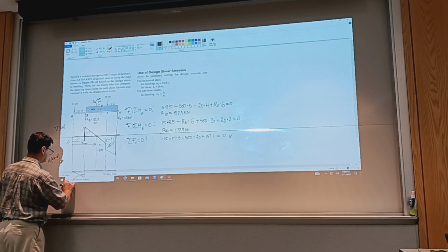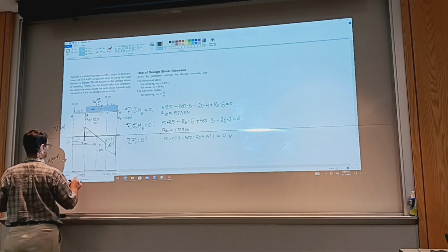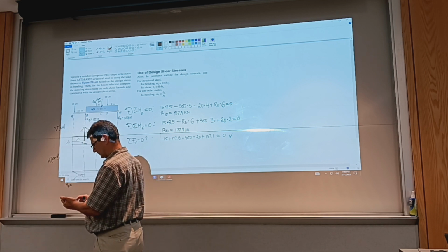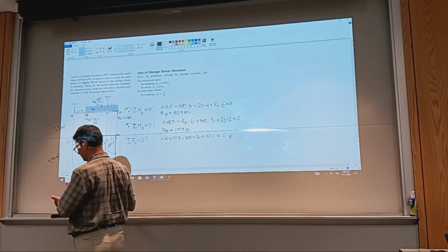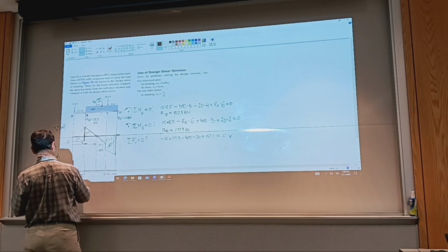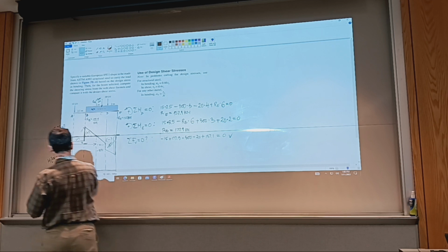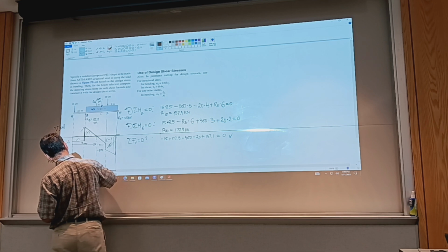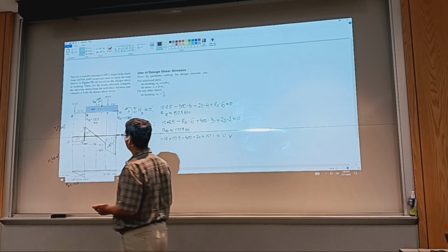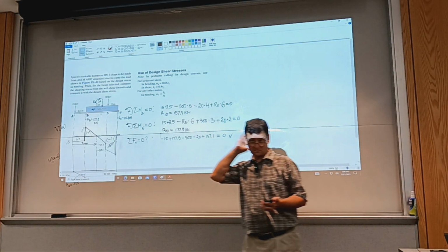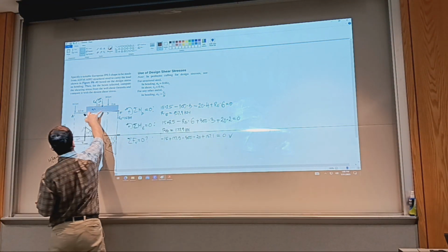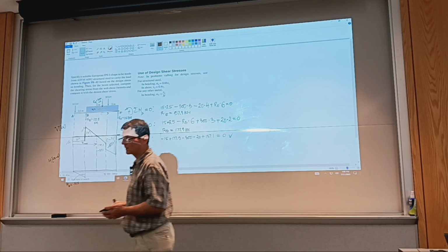And what is the moment at B? Again, a negative value. So it's going to be 15 times 2.5, that's negative 37.5 kilonewton meters, right before point B. We're at point B. And then I continue under the distributed load. So moment switches to a parabola.